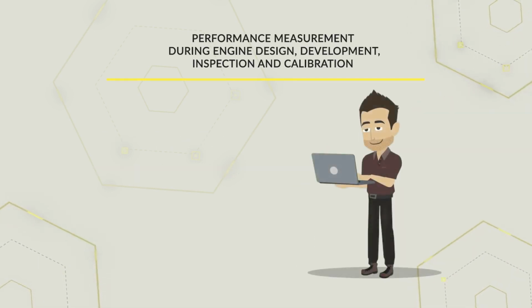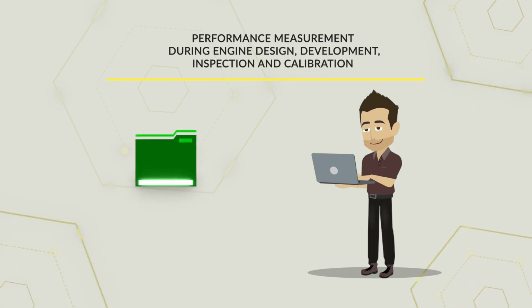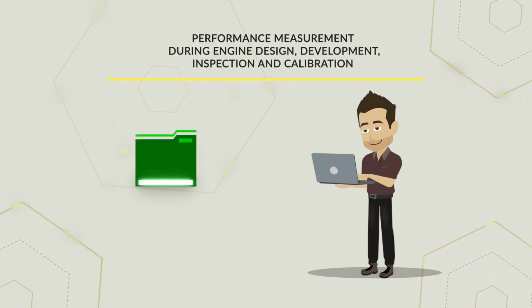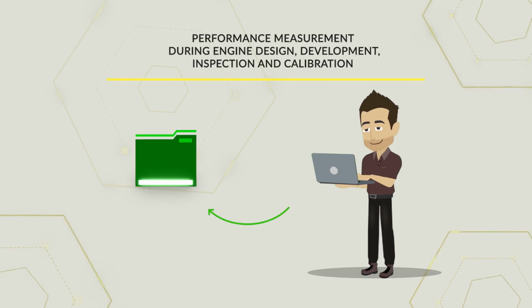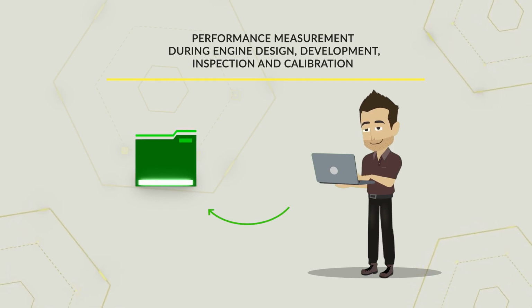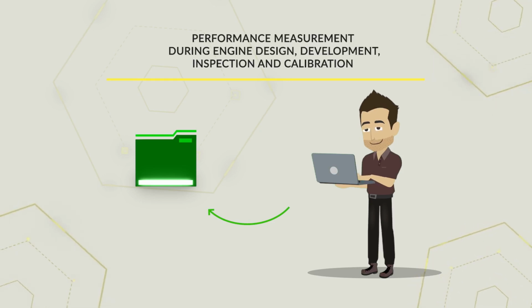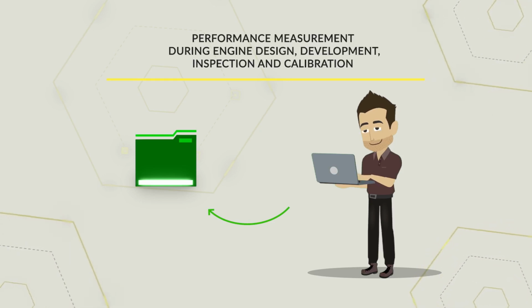After the real control phase, the manufacturer proceeds with calibrating the ECU maps to determine one or more preliminary versions of the original file, which differ in maximum performance, sometimes changing some mechanical parts and sensors, while other times the motor configuration is identical for different nominal powers.